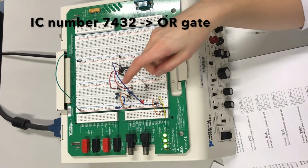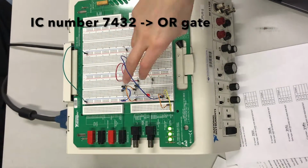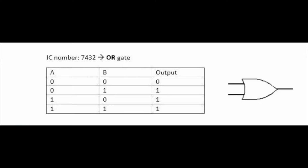Next we used the 7432 IC. We always got positive output except when both inputs were negative. From the truth table we found out that we had an OR gate. The OR gate behaves like the name says. The output is true if either or both of the inputs are true, but if both inputs are false, the output is also false.